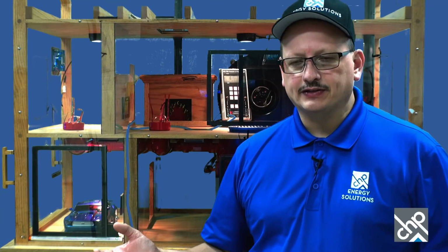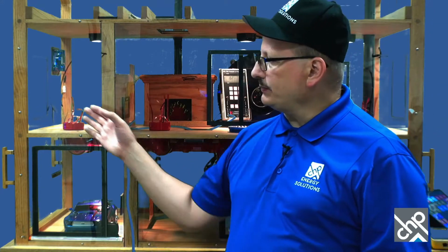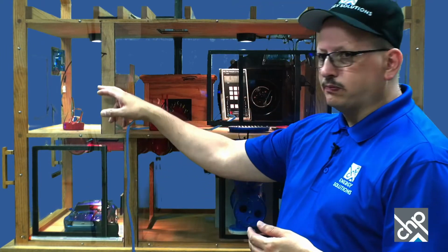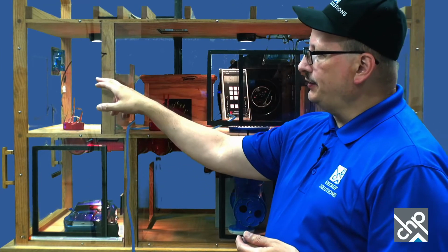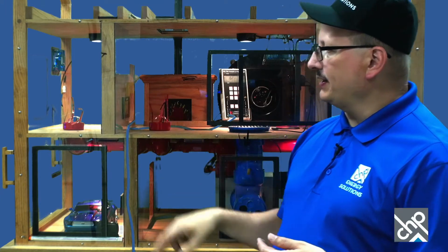But you can measure it to the outside, and the difference is, if you want to know what the pressure is across it to the outside, then that lets you know if you may be pushing moisture in or out of the wall there, the pressure on that wall. If you're measuring the pressure across the interior door here to the main body of the house, that lets you know that it's balanced to the house.